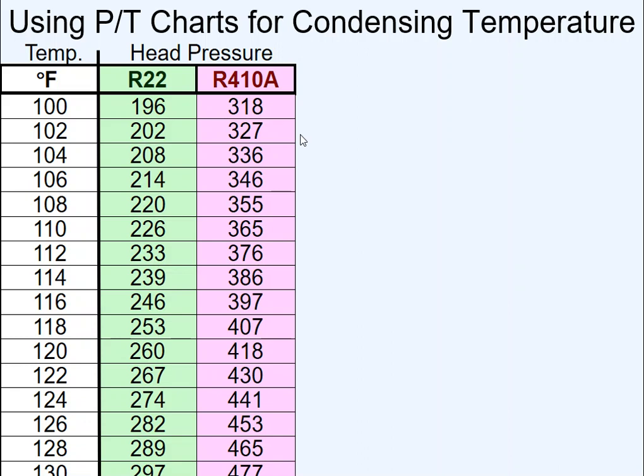So stop. Don't train yourself to chase pressures. Train yourself to know what the temperature should be, and then to verify what it is. That's something you'll hear me say a lot. If you put your gauges on a system to find out what it should read, you've already messed up.